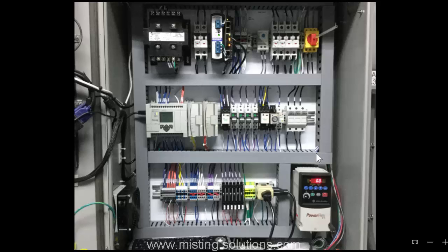Now the DC side, as far as those power distribution terminal blocks, there is one up here. There's 3 positive 24 volts DC and 3 negative 24 volts DC. There's distribution of DC power from there. But also, one of those wires comes down here and goes to this terminal block right here, and from there it jumpers off and goes to other areas within this control panel. So again, these are just jumper points basically. One wire comes in and then many wires go out.